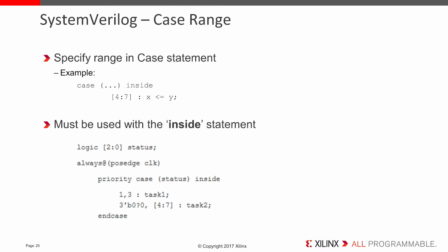Case ranges are now supported for SystemVerilog. Users can specify a range in case statements as shown in the example here. It should be noted that the range must be used with the inside statement.